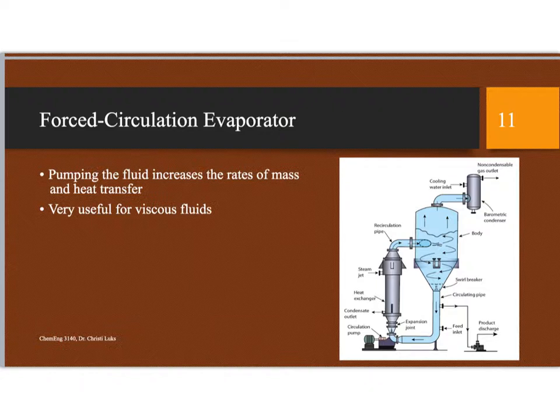Forced circulation evaporators have the fluid pumped around so that it keeps recirculating until it is condensed enough. This is going to be a useful design when you do have those more viscous fluids, so think syrups, something like that.